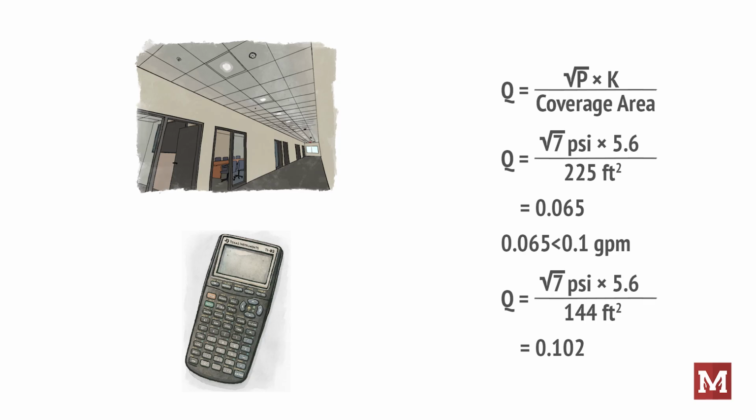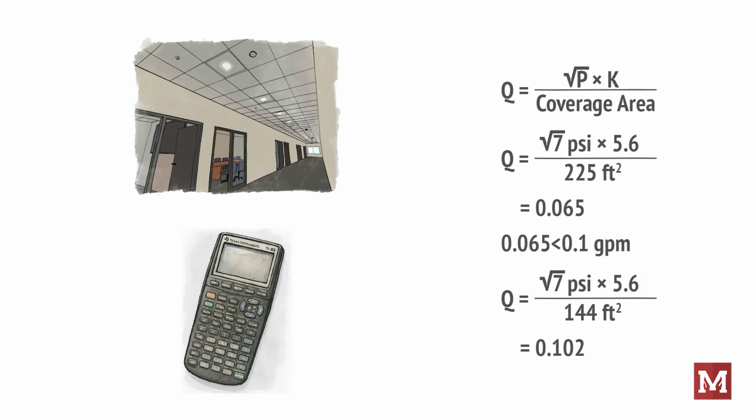Now, that's a pretty basic equation. In the real world, there will be some other things we need to address, but the reason we went through this exercise is to illustrate that sprinkler coverage is a critical component of the sprinkler hydraulic calc. The only thing we changed is our coverage and spacing, and we went from hydraulically inadequate to adequate.